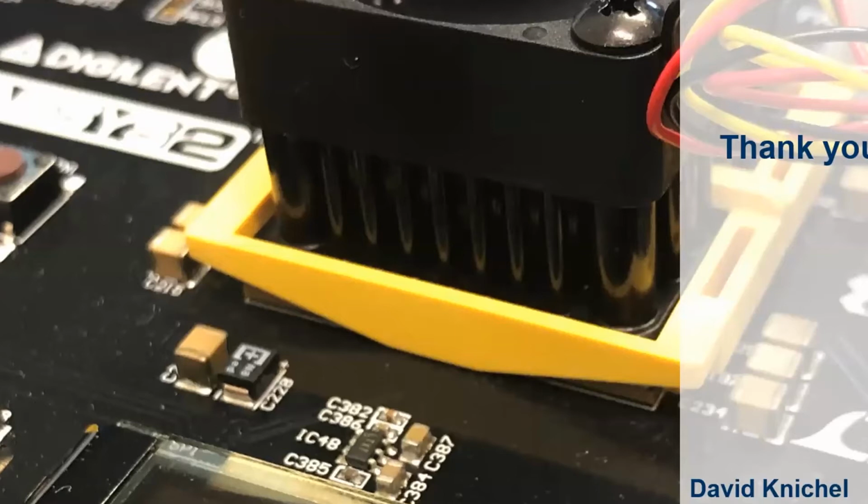Yeah, okay, thank you. May I give a comment here, Matthew? Yes, sure. Currently, if you write your design, for example a Verilog or VHDL design, anything that you define, and then you synthesize it, at the end you get the netlist. And the netlist is just made of binary gates. Then you are able to still analyze these binary gates by this tool. It doesn't matter which consideration you had when you designed the circuit, either binary or any other field.